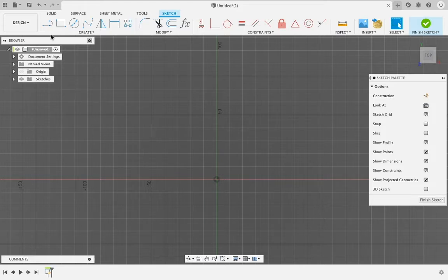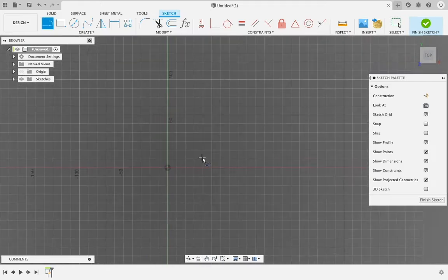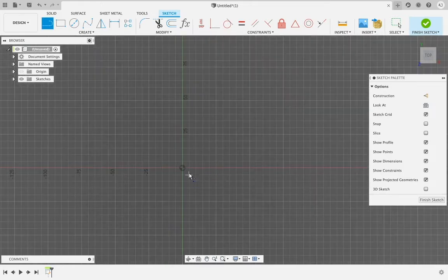Starting off is, ever so basically, the line tool. The line tool allows us to start from a single point. To start, you can select this point and move your mouse over, seeing a measurement in millimeters and an angle at which this will lay. You can select any measurement by typing it in if the text is selected as green, or you can use tab to switch between them to specify an angle. For now, we'll hit tab and go into the measurement zone.